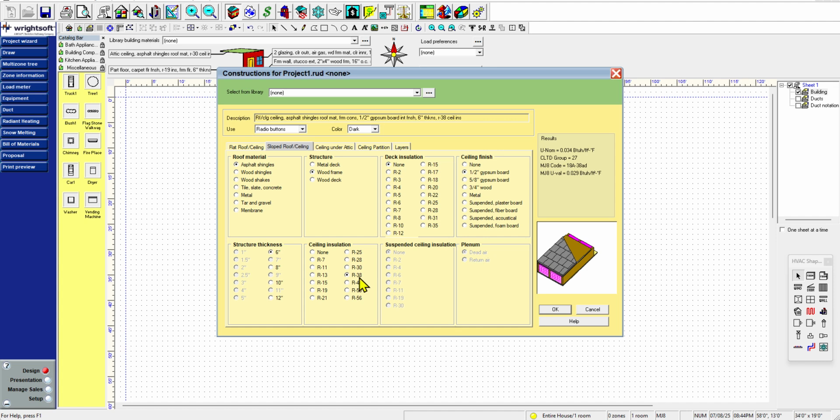So let's see what happens if I were to use less insulation. This number would go higher. All right, you see that? So R7 would be a thinner insulation, or a not as good insulation, and the U value went up. As the insulation gets thicker or better, the amount of heat that gets transferred is less. So the overall heat transfer coefficient will get smaller as the R value number gets higher. All right. So we've got our 0.29 number.